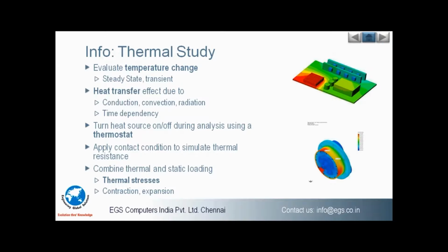For the heat source or the thermostat condition, we can directly turn it on and off during the analysis based on the real-time conditions. Using this, we can also apply certain boundary conditions or contact conditions for the designs. By this, we can evaluate the thermal stresses, either a contraction or an expansion, for the thermal studies.